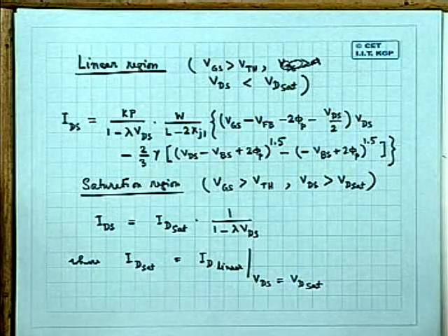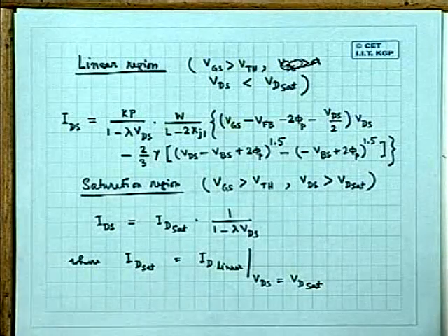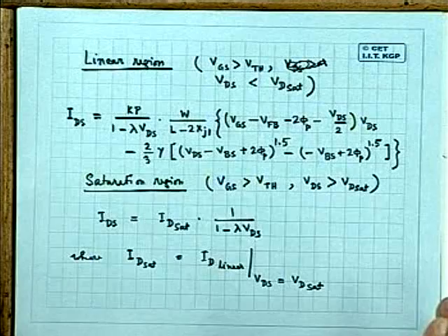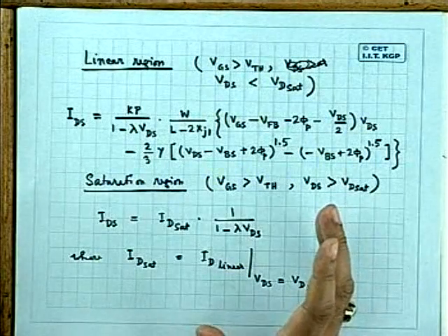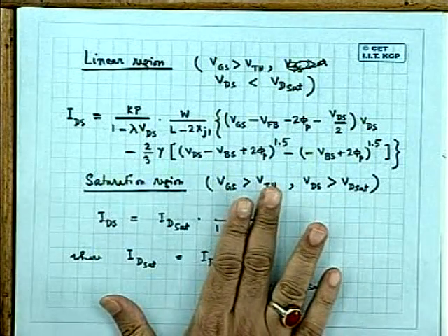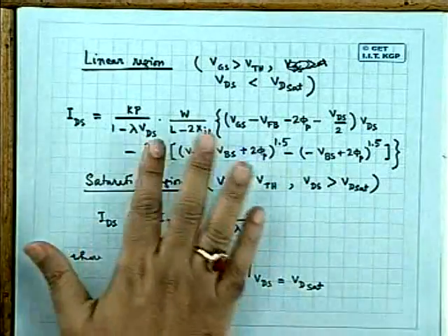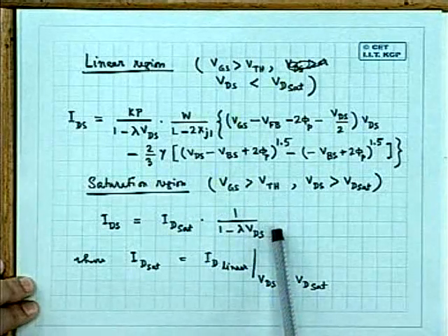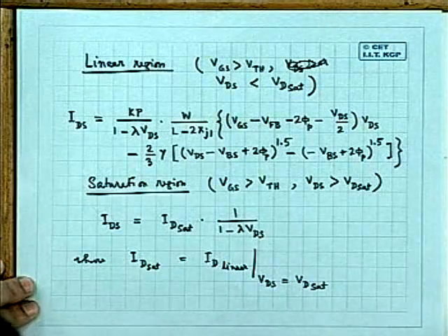While fitting with experimental data, they found that modeling the current equation this way can push these devices into the micron region. Otherwise, if I do not consider this, the equation is more or less okay for up to 3 micron or 4 micron, but below 3-4 micron, if you want to validate the model, they found that putting this in as a multiplier becomes more accurate.